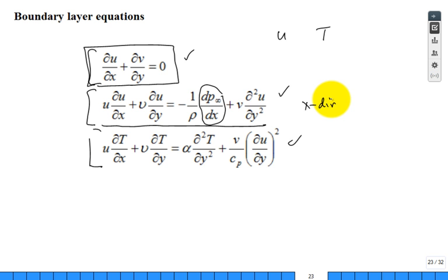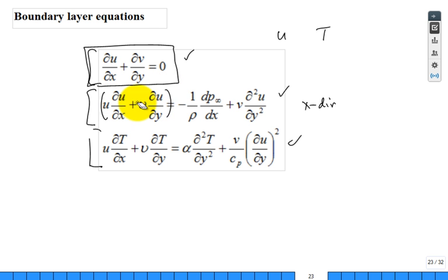All right? Basically, the fluid, once it hits a little bit above that, you're looking at the flow in the boundary layer above the surface of the plate. It's slowing down in the x as the momentum is felt, the viscous effects, further up above the plate. Isn't this how the diffusion of momentum percolates or moves and is felt in different layers further and further into the fluid above the surface? Yes. And what is this? The advection of momentum.